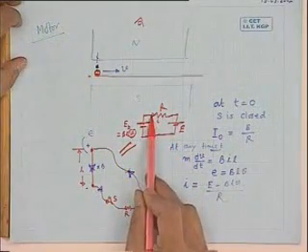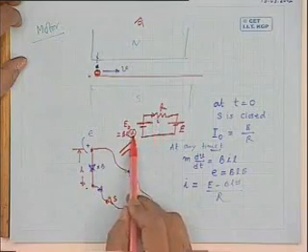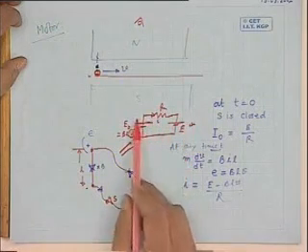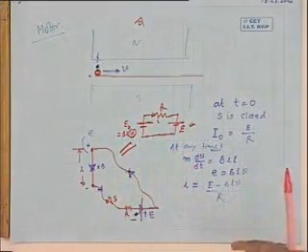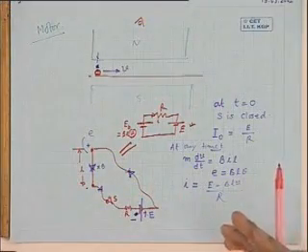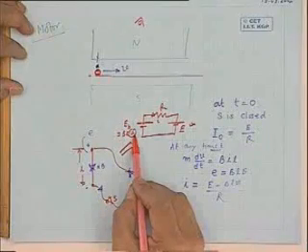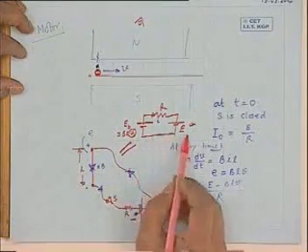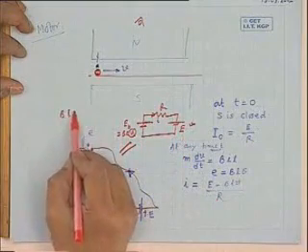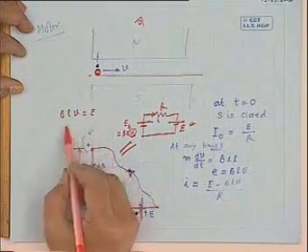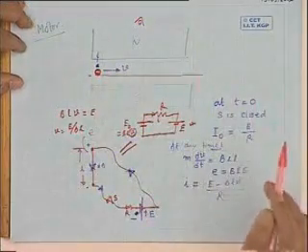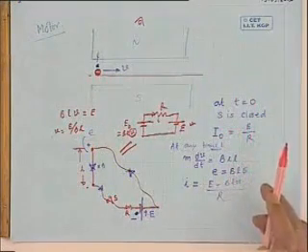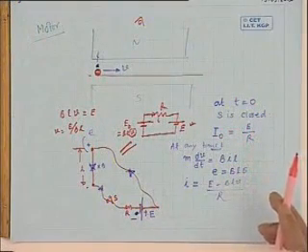So in this way, it will go on accelerating. Finally, a time will come when I will become 0, because when this back EMF becomes exactly equal to E, the current will become 0. And the accelerating force will vanish at that time. So the conductor will not accelerate further, but will continue to move with a constant velocity. So what is the value of that constant velocity? It should be such that BLV equals E, that is, V will be E by BL. At that velocity it will continue to move.